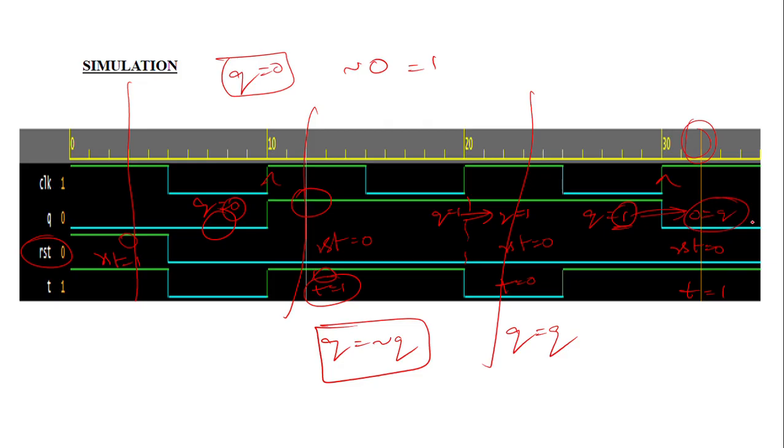Like that you can cross-check whether your design code or functional table is matching with your waveform or not, and whether you are giving correct values to your test bench code or not. So cross-check both your design code and test bench code against your waveform and functional table. If you get any errors, try to rectify them. If you still don't get a solution for a particular error you didn't understand, simply comment on it, and I will make a small video with a small clarification on that.